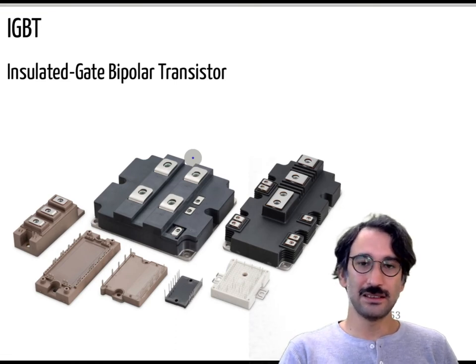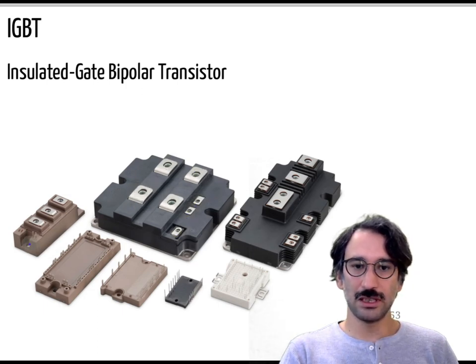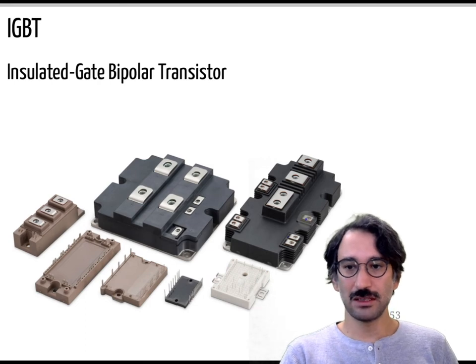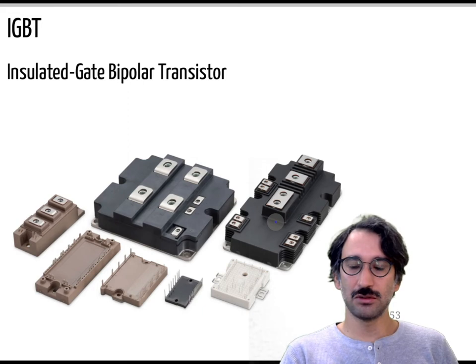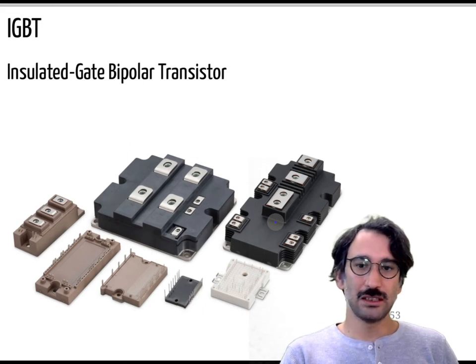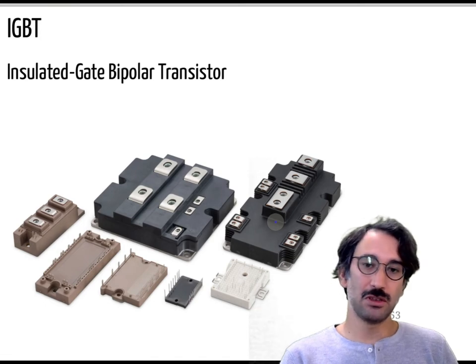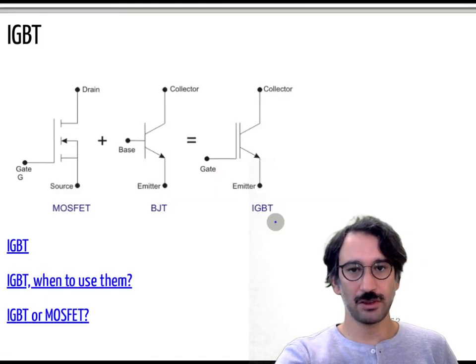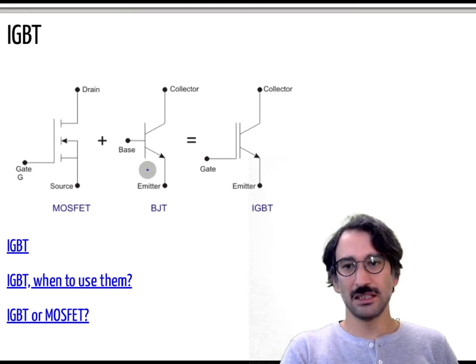You can have the 6 IGBTs, and those large terminals are for power, and small terminals like that one, or small terminals here, they are usually for gate signals, or in some cases you have some self-protection circuits inside those modules, so it can give you an error if temperature has gone above the limits, or if the current is too high, etc.